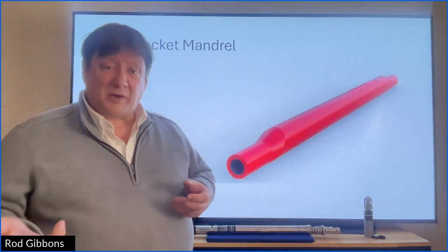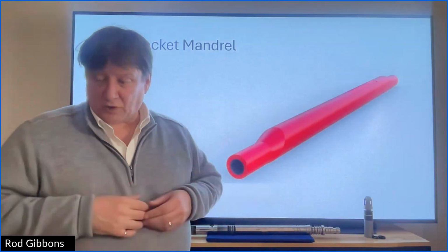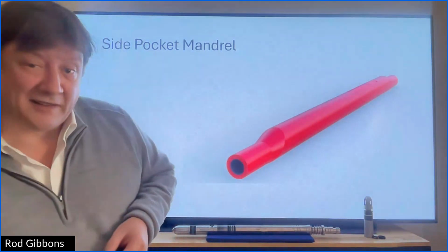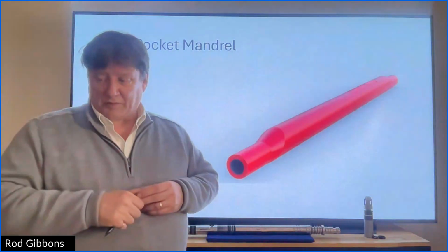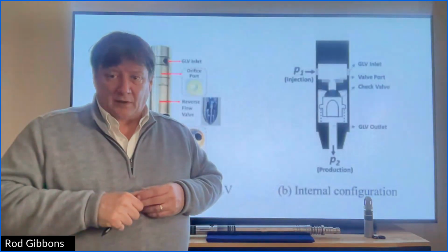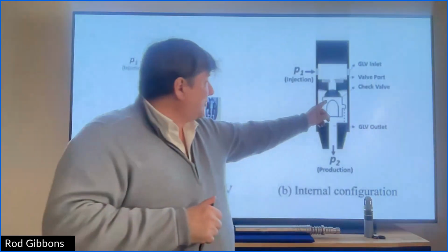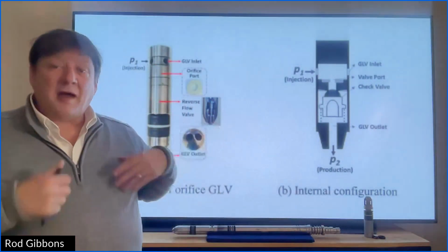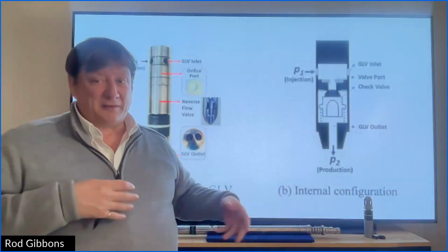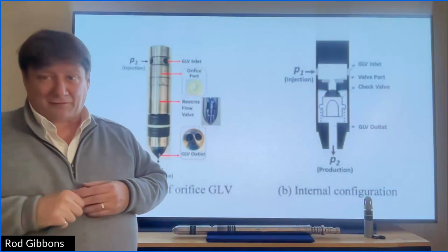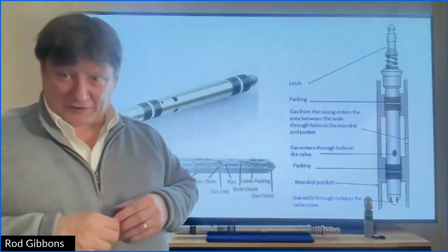You don't have to come back on the well and do an installation, especially for something like subsea wells, where it's pretty pricey to come back. So, yeah, we had a look at the check valve, the check port. Once we get reservoir fluid in the well, then we don't want to have stuff flowing out into the annulus.